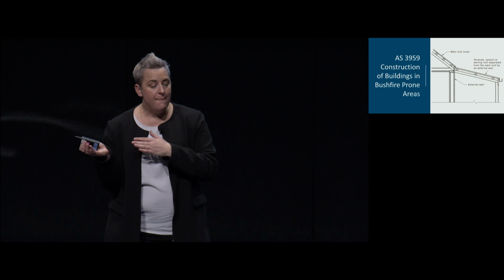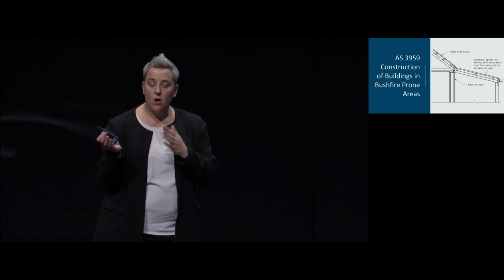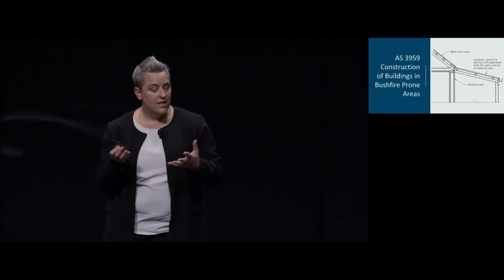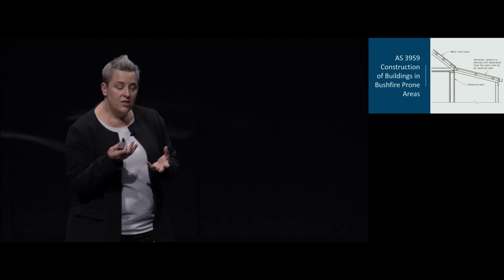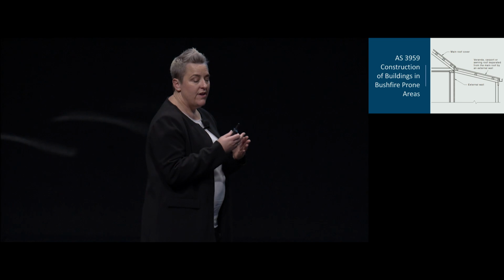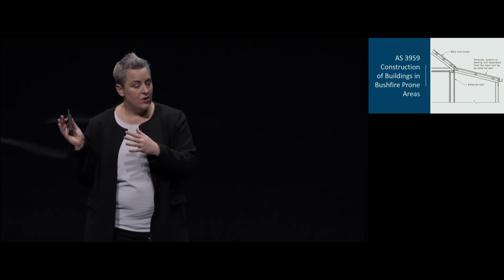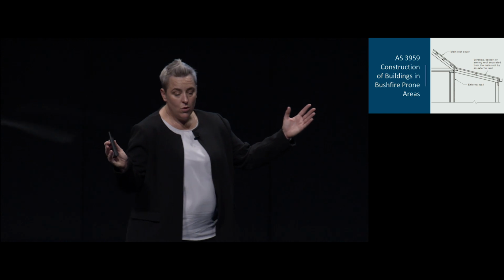Where your slopes vary but fall within the specified range given by the standard, it clarifies that there's no need to take separate assessments. There is an exemption to this: where the slopes vary over 2 or more ranges, it clarifies that you do have to do separate assessments.